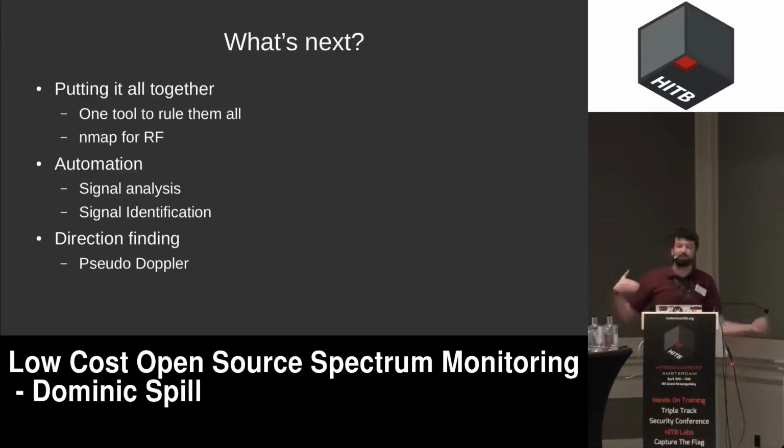What this presentation is about is trying to show which tools exist and where we'd like to take them next. That's what I'd like to talk about for just another minute or two. We would like to be able to have the capture and the visualization and the analysis all in one tool. We'd like to build an open source tool, preferably, that will allow us to receive that 6 gigahertz of bandwidth, and then when we identify a signal that looks interesting or novel or different, we can drill down into it and take a look at what kind of modulation it is using. Let's do a spectrum plot to see if we can tell what kind of modulation it's using. Let's try and decode it in some way.